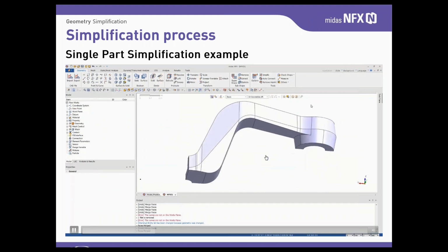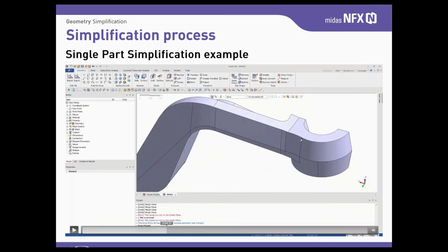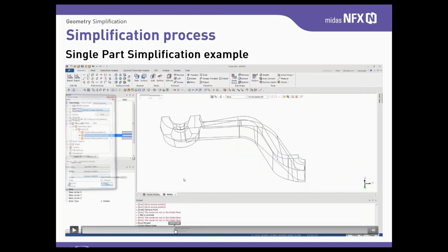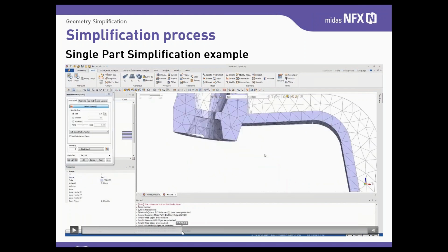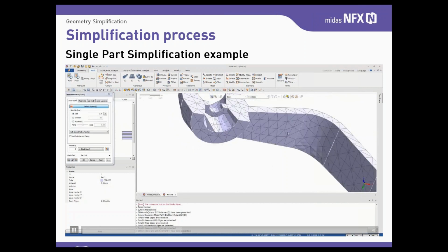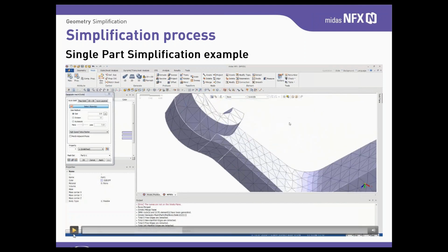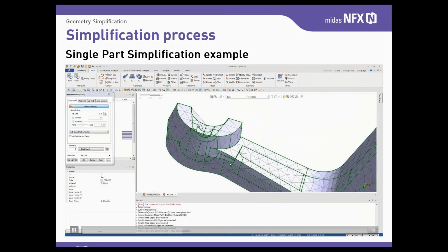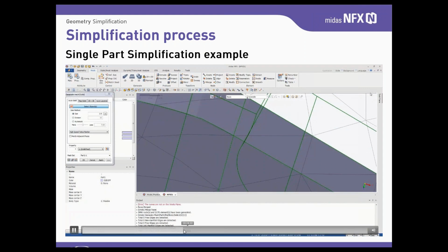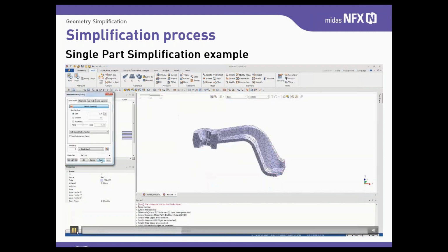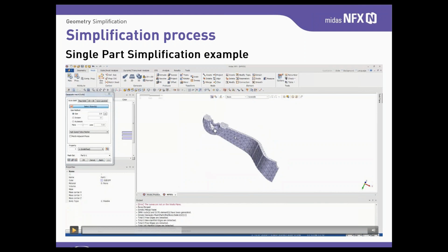So everything looks really nice, but I met some problem with meshing. So if we go to the mesh, and if we rotate this object, you can see that some element is outside the geometry. So this means something is wrong with my geometry. I will go back a little bit, and I will pause again. I'm talking about this place, which means I still have to find a solution to fix this geometry.